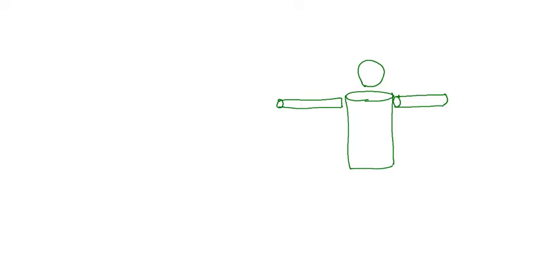Maybe her legs are part of her torso there, or if you want to really get fancy, then there's a way that we can do that as well, called the parallel axis theorem. But these shapes are on the table, right? When we go back to that table, we recognize her head looks quite a bit like a sphere, and the moment of inertia of a sphere was 2/5 mr squared. Now, of course, that's the mass of her head times the radius of her head. Okay? So it's not the mass of the whole skater, just her head, just the sphere part.